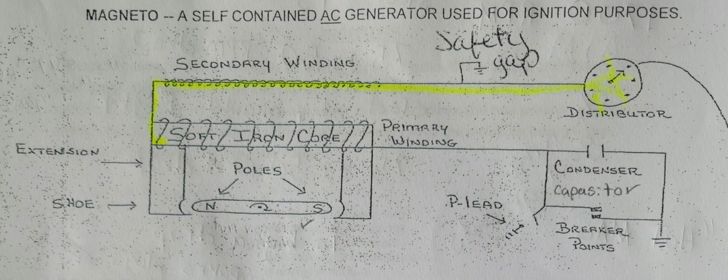What is the purpose of the condenser in a high-tension magneto-electrical circuit? Prevents arcing at the points, hastens the collapse of the magnetic field. Where is the E gap position? A few degrees past neutral, where the points begin to open.